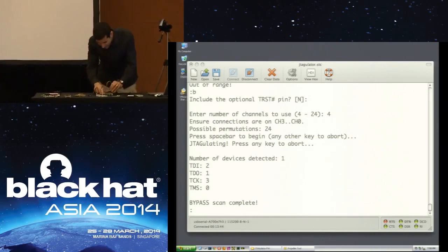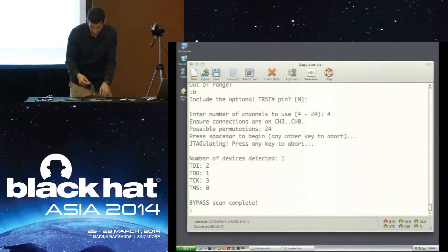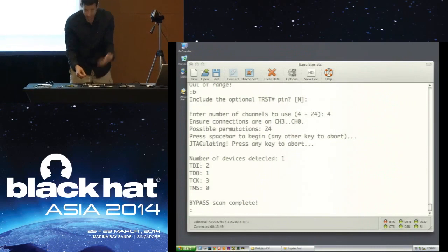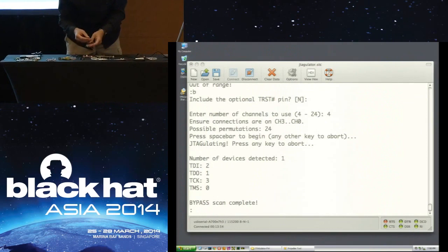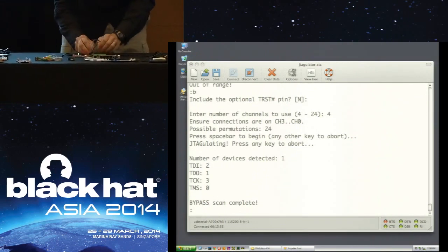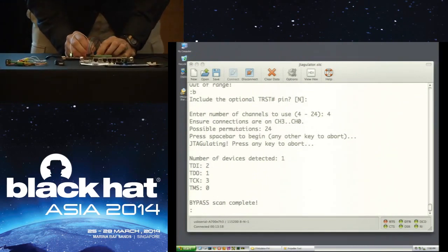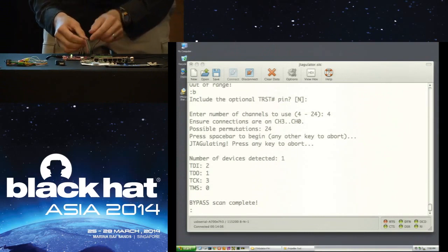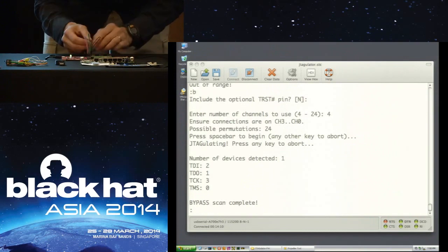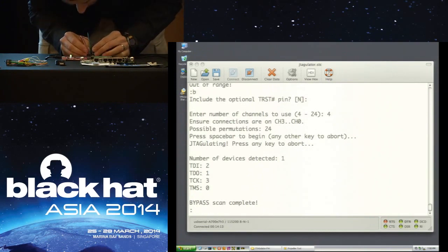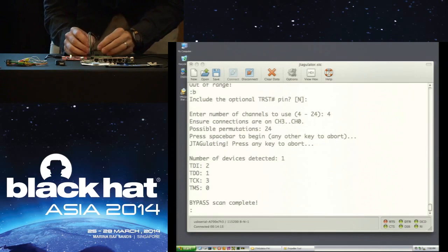I'm disconnecting the JTAG cables, and I have a bunch connected to the UART, which now I know is the UART, but I don't remember what the pins are, so I'm just going to connect these up. It's a 2x5 row header, and I'm looking at one side, so there's 5 pins. I have ground hooked up, and then 4 other pins, so I'm going to connect those to CH0, 1, 2, and 3, just like I did before. And I don't care how they go in.